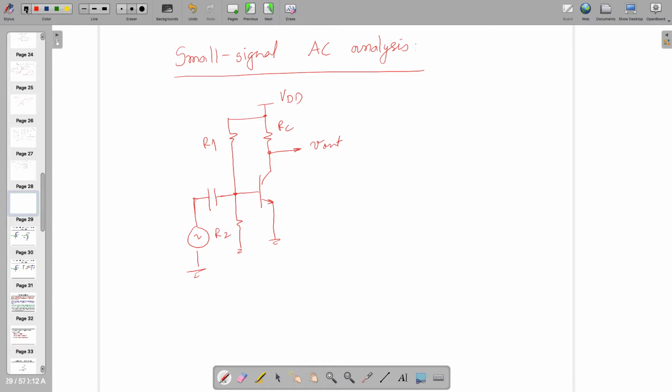You have to remember the following thing. This is an AC analysis where AC sources will be activated. However, all DC sources will go to 0. This is because we are doing an AC analysis. Get the remark?